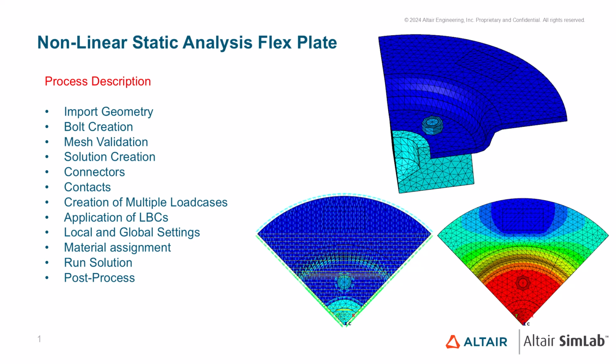In this video, we will demonstrate how to set up a nonlinear static analysis with multiple load cases. The first load case will address the pretension of our model, and the second load case will involve the applied load.